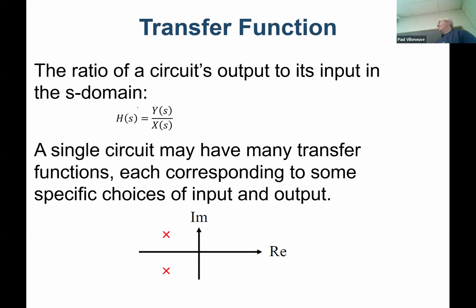And now what I'm going to do is basically say, well, how fast is something? Or how much does it oscillate? How much does it overshoot? And you can look at these pole zero maps and determine what the performance is based on the location. The x's are the roots of the denominator. These are the poles. What do you think would be the symbol we would use for zeros? A 0. A 0, yeah. Let's make it a 0. So it's really obvious, right? The zeros are denoted with a 0, and the poles are denoted with x's.